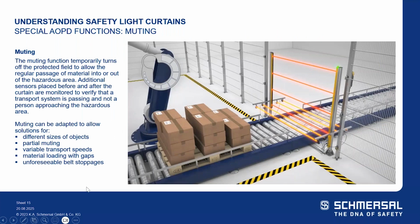Muting. Another special light curtain function is muting. Muting will temporarily turn off the protected field to allow the regular passage of material into or out of the hazardous area. Additional sensors placed before and after the curtain are monitored to verify that a transport system is passing and not a person approaching the hazardous area. Muting can be adapted to allow for different solutions for different sizes of objects, partial muting, variable transport speeds, material loading with gaps, or unforeseeable belt stoppages.